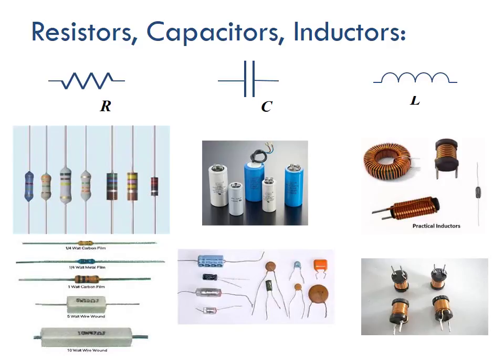And if you guys want to see a burnt out resistor, I have a couple from previous projects that people have done. They go completely char black usually, kind of cool to look at. But essentially, you size your resistor for the amount of wattage that goes through it. And remember, watts is power. Power equals current times voltage. And also you can substitute V equals IR into that to be able to get power from current and resistance or whatever different values you have available.